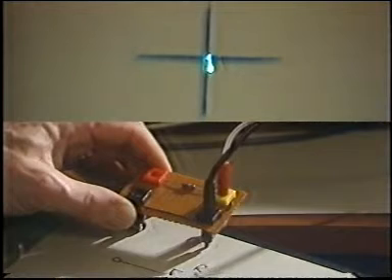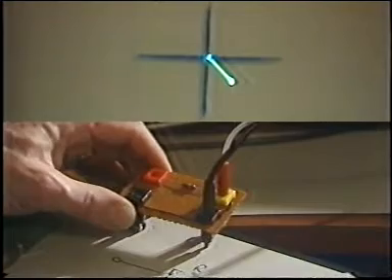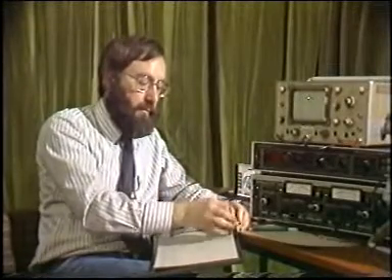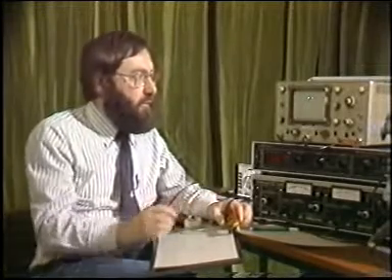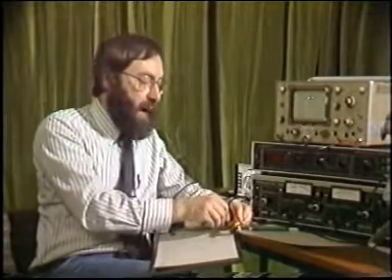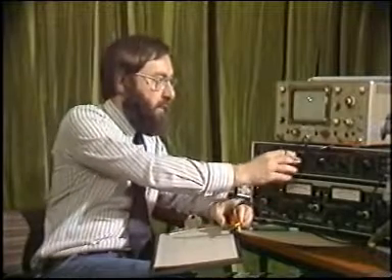And I'm now reducing frequency, coming back to more or less where we first started. Now, I want to have another look at the input phasor. You remember that this is held at constant amplitude and at zero reference over all frequencies, while the output phasor varies in length and angle as a function of frequency.